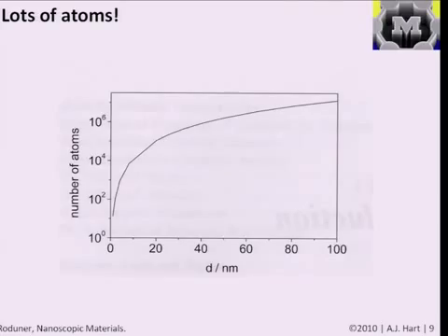But without a doubt, things that are even the size of our hair contain massive numbers of atoms and massive numbers of structures. And one of the very practical and useful and important implications of that is that if you have very small structures packed together, you have a lot of surface, because the ratio of surface area to volume increases as you go down to the nanoscale. Because if you do the math, which we'll do next time, to take the surface area to volume ratio of a sphere, you'll see that it scales with 1 over the radius. So a smaller sphere, a smaller particle like this, can expose a lot more surface. And if you have, say, a powder made of these C60, these buckyball particles, you have a material with a very high surface area, and that can be useful and interesting for a lot of applications.